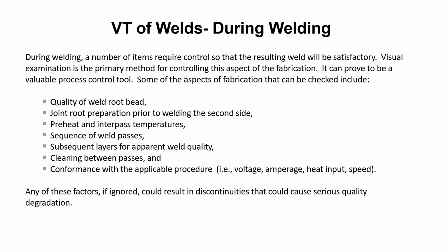Are they following the procedure? Voltage, amperage, heat input, these kinds of things. And once again, any of these factors, if we ignore them, could result in flaws, defects, discontinuities, that we could have some quality degradation. We could have issues, problems later on. So these are some things we need to take care of and look at when we're talking about welds.